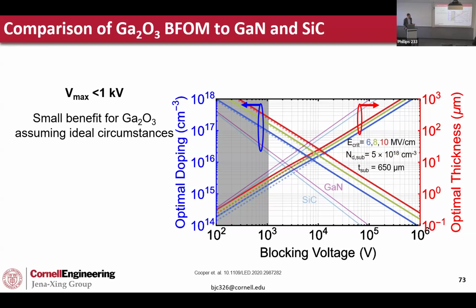So there's not too much of an argument for moving to a material system like gallium oxide, where you do have the issues of thermal conductivity, the mobility is significantly lower, and as to GaN's benefit, we don't have polarization. So this was already noticed by many other people, but now we're visually seeing from 1D approximations why in the low kilovolt case, gallium oxide is not very competitive, though it may still have its niche uses depending on if you're at radiation or high temperature.